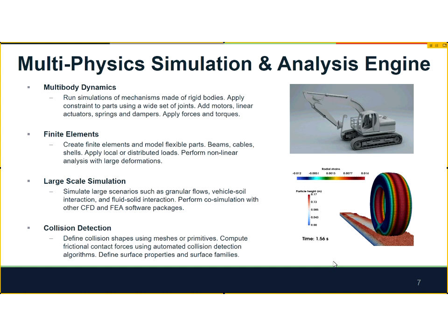And then here's just an example simulation from the tool showing the FEA, and this is a model of a tire rolling through granulated earth, and you can see it's capturing the deformation of the tire in interaction with a pile of particles on the ground. And so this fundamentally is a capability that we need, capturing the deformation of a 3D mesh and interactions with granular material.